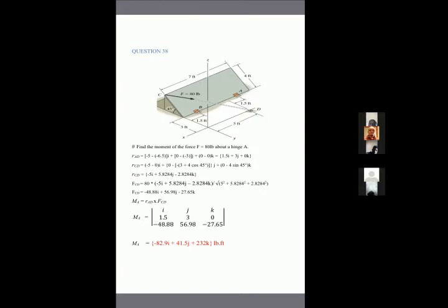Then point D in the Z doesn't move anywhere, so it's 0 minus point C in the Z. It has moved 4 sine of 45. So we have our RCD, which is equal to negative 5i plus 5.8284j minus 2.8284k. Once we have our vector RCD, to get the unit vector, we simply divide the vector by the magnitude of CD.